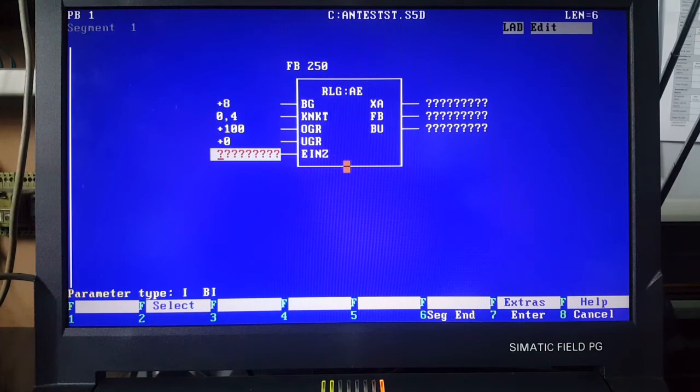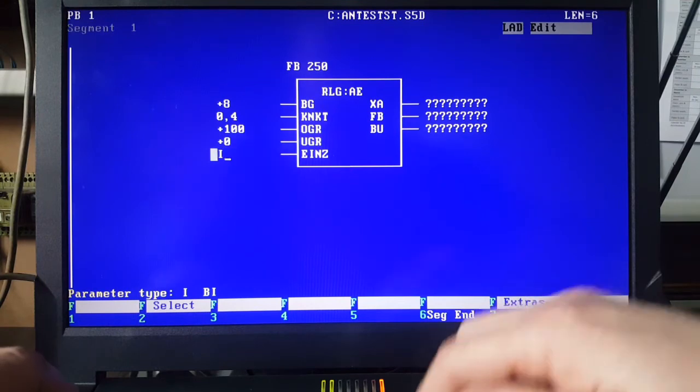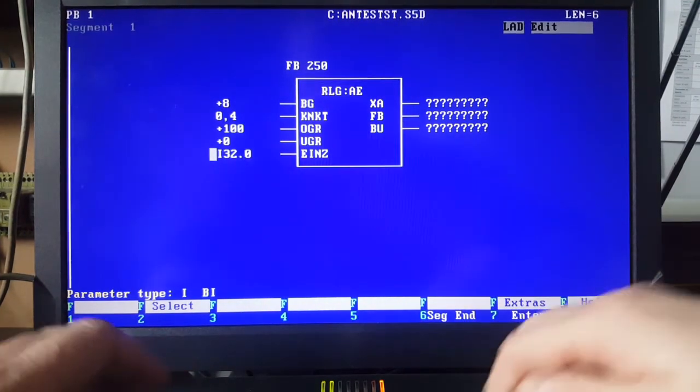INS is the next parameter we come to. INS is Boolean and will accept a flag bit, for example. If this is set to 0, then the block will read from the process image. If set to 1, then the block will read directly from the I/O. If you want to read the analog value cyclically into the I/O image, then you will need to set the appropriate parameters in DB1. So for this exercise, I will read the values directly, so I'll need to set this to 1 when we come to test the program. In this case, I will use input 32.0.